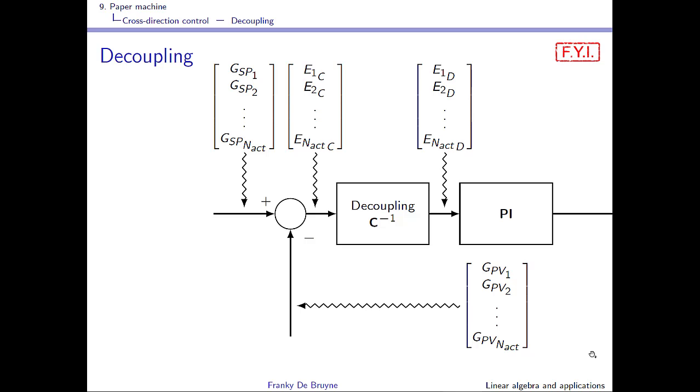For that you also need a model of the system. This is all explained. If you have a model of the system, then you can start testing things on your PLC on this model, and for instance, see what happens if you have chosen the wrong mapping, or the wrong decoupling.